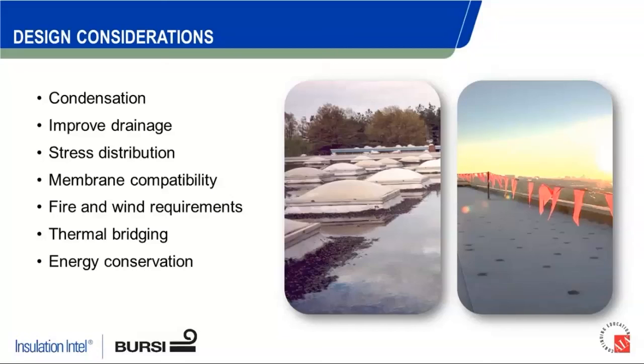All materials don't play well with each other, so it's important to know the type of membranes, the type of insulation, and the adhesives you're using, and how all of the different components will interact with each other. And that whole roofing system, including insulation, needs to be designed to meet the fire code requirements for that building and roofing system, and wind uplift requirements. That has a lot to do with the location, the height of the building, and several other requirements that fall into the understanding of the wind uplift requirement of that system.